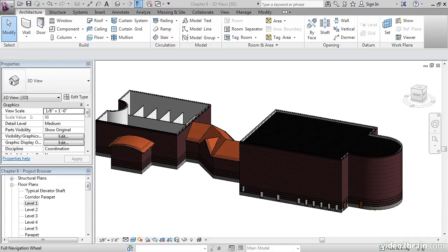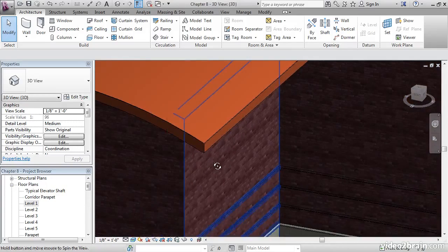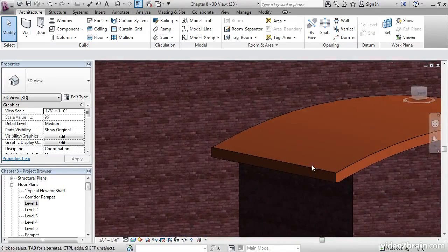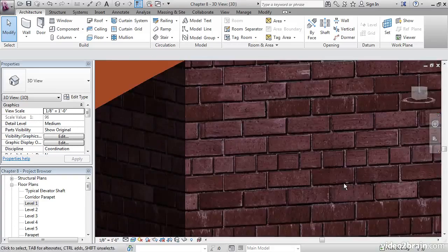There actually is a separate command in Revit called roof fascia, unlike the absence of the roof dormer command. The objective of this exercise is to add a fascia to the corridor and the southwest curved roof. Open the file you've been working on, or open the file called Chapter 8 and follow along. As you can see from my example, I have the dormer finished off. Boy, it looks a lot better, right? Kind of cuts it in, trims it up nice.